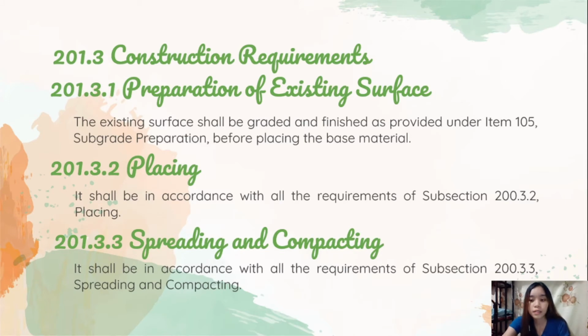Next is the construction requirements. First is the preparation of existing surface. The existing surface shall be graded and finished as provided under item 105, which was already discussed by the previous reporter, and subgrade preparation before placing the base material.